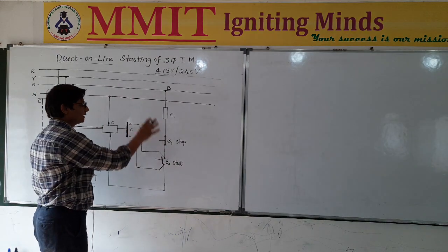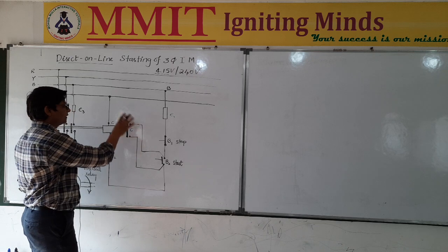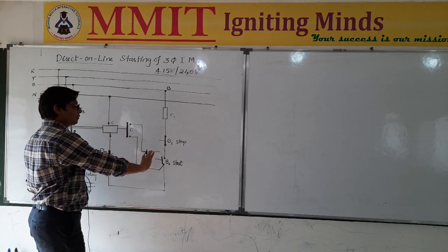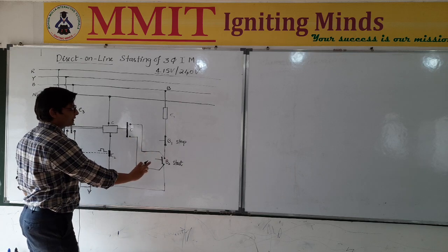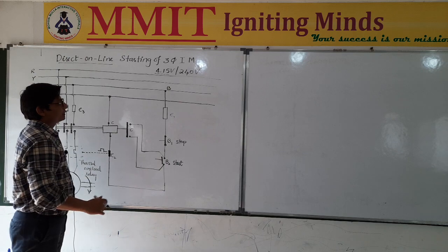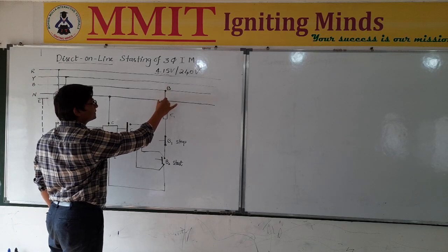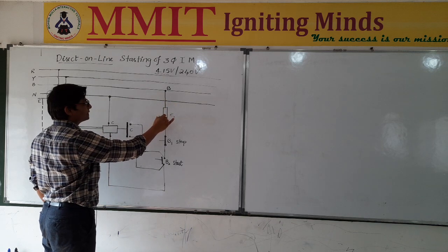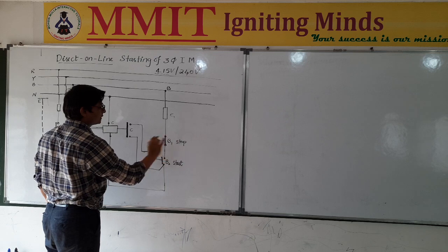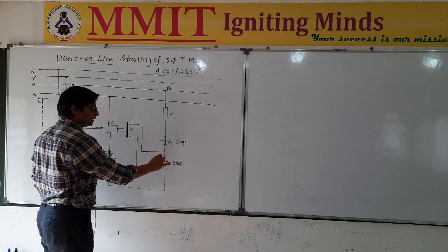Okay, so that is connected with the help of different elements, electrically, in a completely controlled way, and a proper electrical circuit connection should be made for that controlling part. So therefore, to do that, here one of the phases is taken. Now this phase is connected with the help of one fuse to the first push button, which is the stop button B1, and then this is connected again to the second push button.